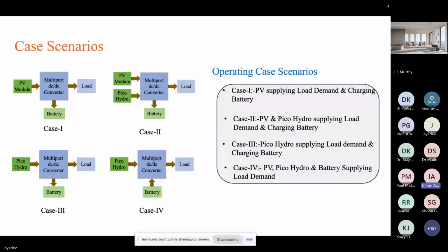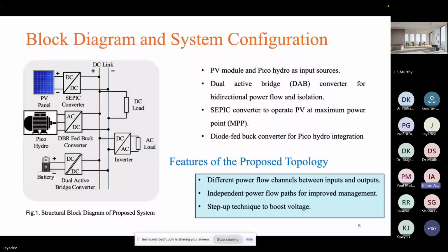Sir, one question. Can the DAB be used for multi-port, or for more than one voltage rating, since it has one transformer? Yes, sir, you can have a tapping at the secondary side. If you are giving 48 volt, your tapping can be 110, 220 and 400 also, according to your transformer design.